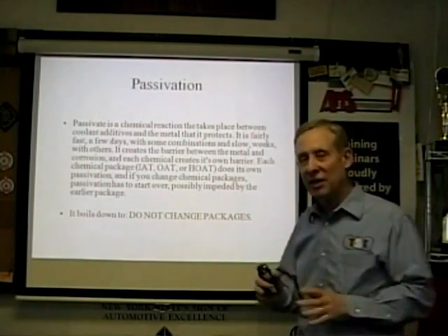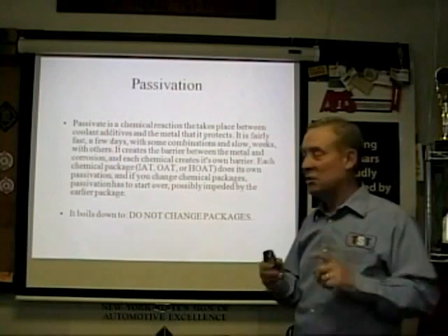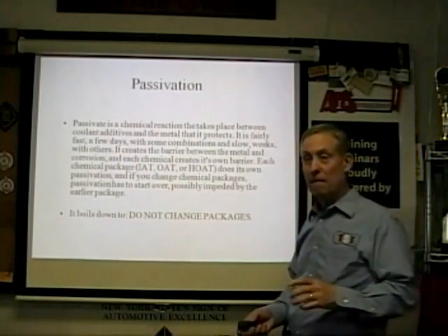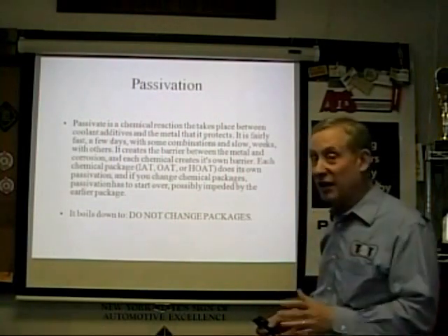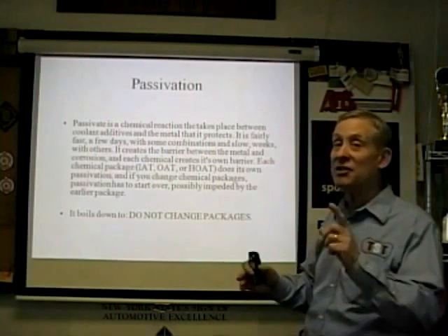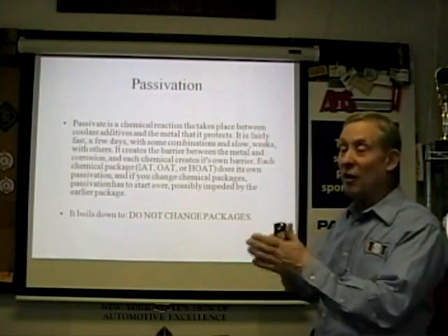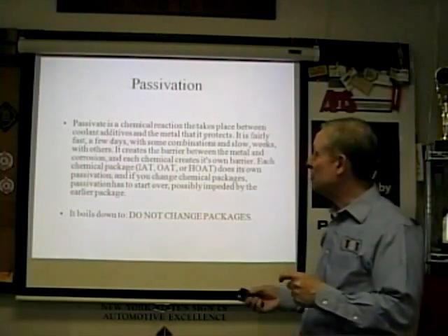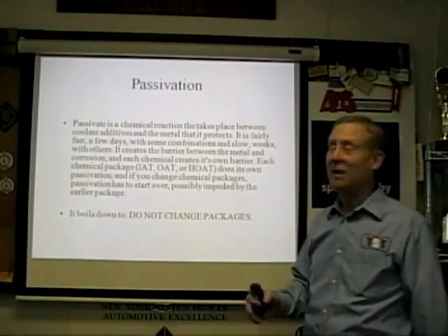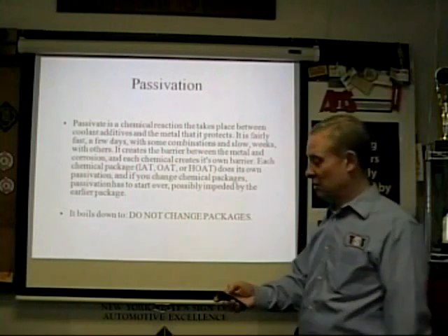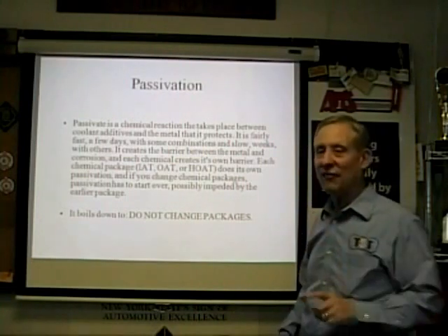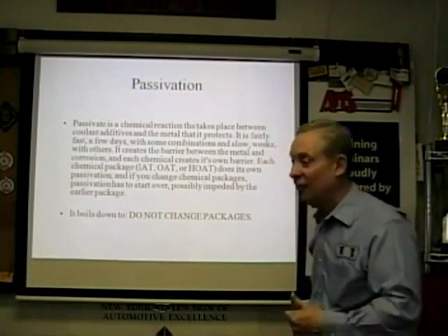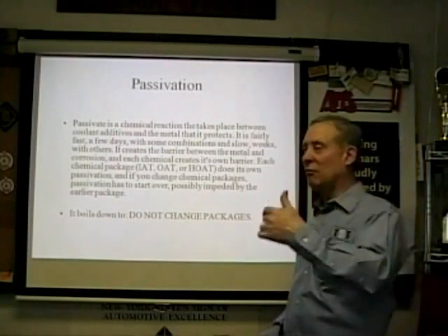It's the corrosion inhibition process, but they use different chemistries, even within the same manufacturer, from one date to another. They make changes in their coolants, and that changes the passivation, and they're not compatible with each other. Again, what you really have to know is don't mix this stuff, flush the car, put the right stuff in.